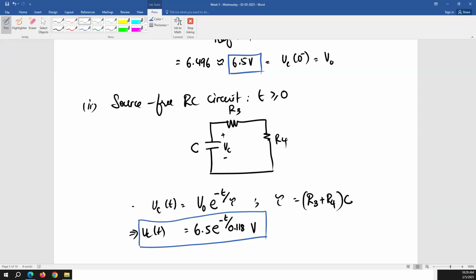You're trying to find a value of capacitor such that when you multiply it with the load resistor you have connected, your time constant is large enough such that the capacitor will hold its charge until the next waveform arrives and the capacitor starts charging again. So that's the time perspective of the RC filter that you have used. So they were playing with the time constant over there.